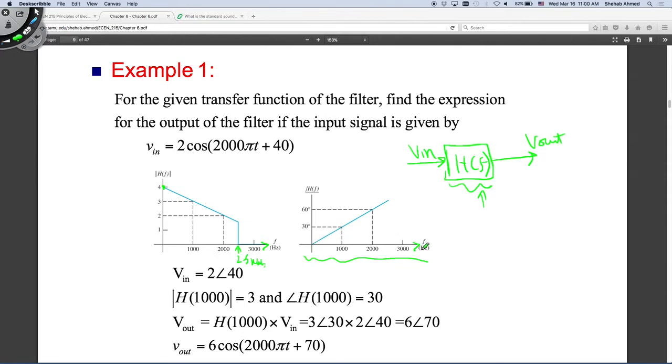As you increase the frequency, the phase shift of this transfer function changes. So you have a signal coming in, let's say this is V1 angle theta. It's coming into this h of f, and h of f is acting upon this signal, so it's changing this signal. You have a signal that is acted upon by a transfer function, meaning it's modified by that transfer function. So you have a complex number and another complex number that's affecting it.